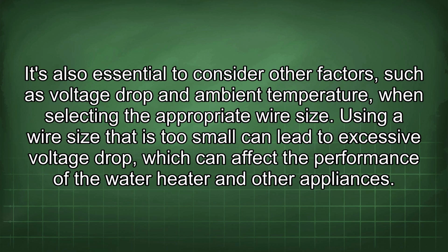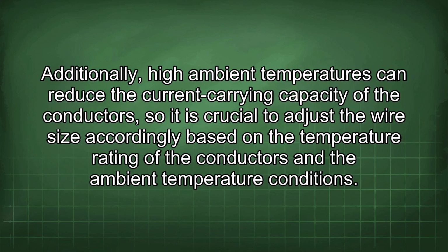Using a wire size that is too small can lead to excessive voltage drop, which can affect the performance of the water heater and other appliances. Additionally, high ambient temperatures can reduce the current carrying capacity of the conductors, so it is crucial to adjust the wire size accordingly based on the temperature rating of the conductors and the ambient temperature conditions.